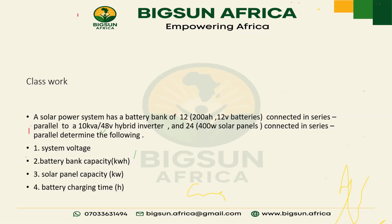It's going to give us 28,800 watts, right? And our panel capacity is going to be 400 watts times 24. 400 by 24 is going to give us 9.6. Our solar panel capacity now is 24 pieces of 400 watts, so 400 watts times 24 is 9.6 kilowatts, right? Yes, sir.